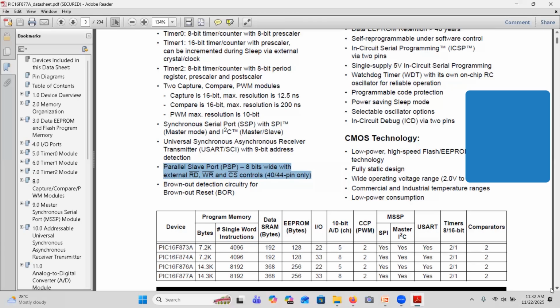So if that is the case, I2C is not required for me. Though the circuitry is there in the microcontroller, I won't use it. It will be there, I won't configure it. I won't use it. But I require SPI. Then I will configure the SPI and use it. I require SCI communication to communicate with the PC. I will use SCI. I want the parallel slave port to interface a display with my product. I will use the parallel slave port.